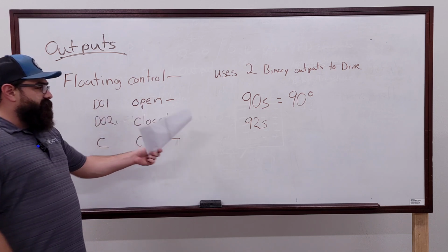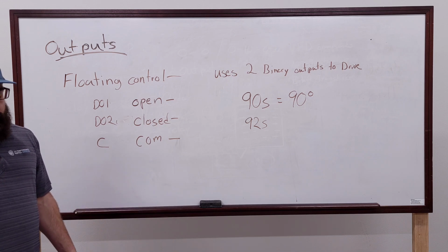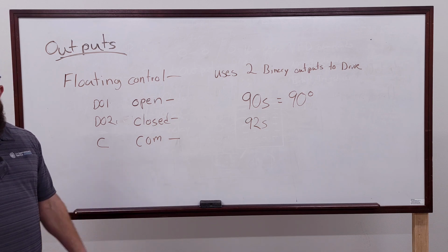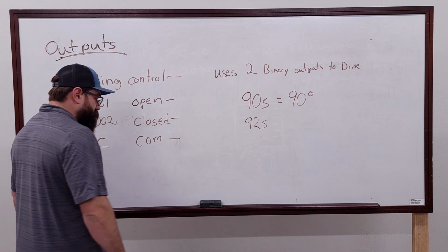Luckily, we don't see these a lot on valves. It's usually just on VAV boxes that is the most common place for them. Most valves and stuff have the true 0 to 10 modulating stuff, so you don't really have to struggle with it too much.